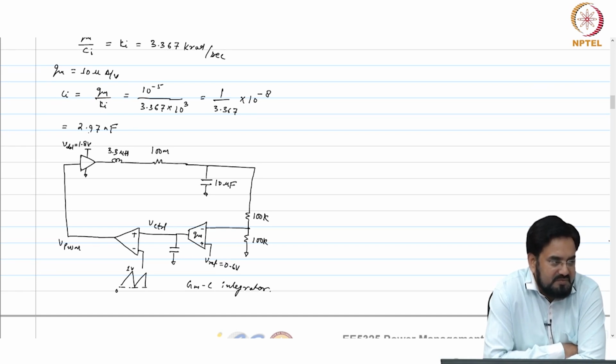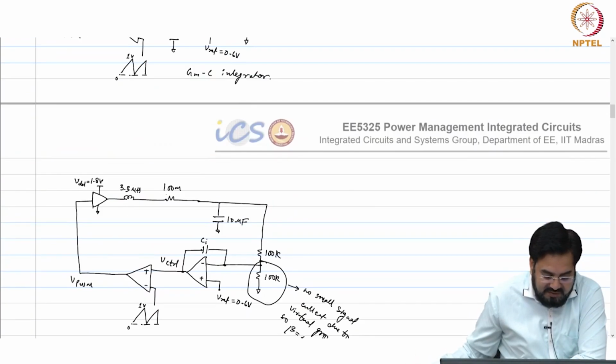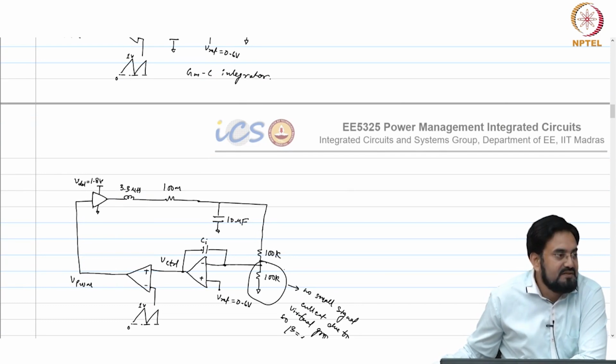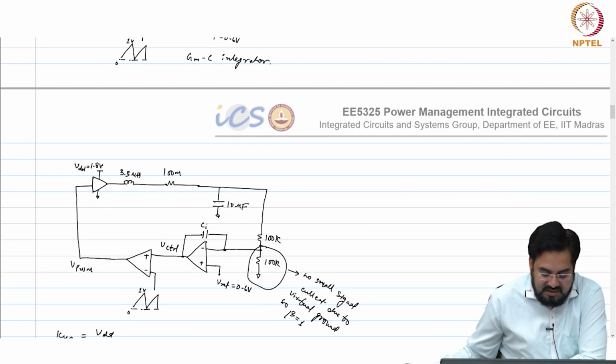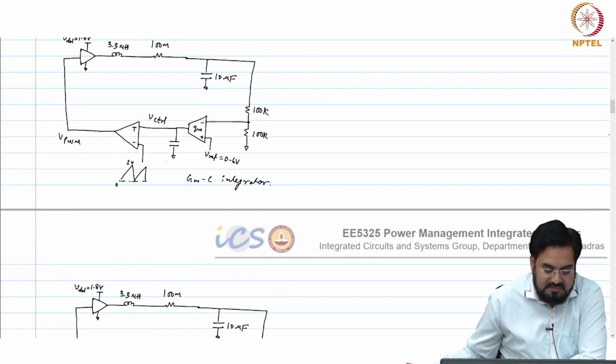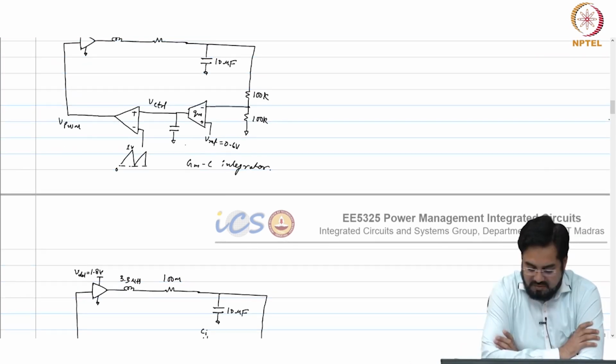I mean, anything less than 100 picofarad is okay, and if it's tens of picofarad, that is more preferred because these caps take a lot of area. So, with the GMC you can achieve that, and if you want to go with the op amp RC, then this R value should be very large, okay, which means this R will take more area. So, it's better to reduce the GM in that case, but there is a problem if you go with a very low GM. Noise is the other thing.